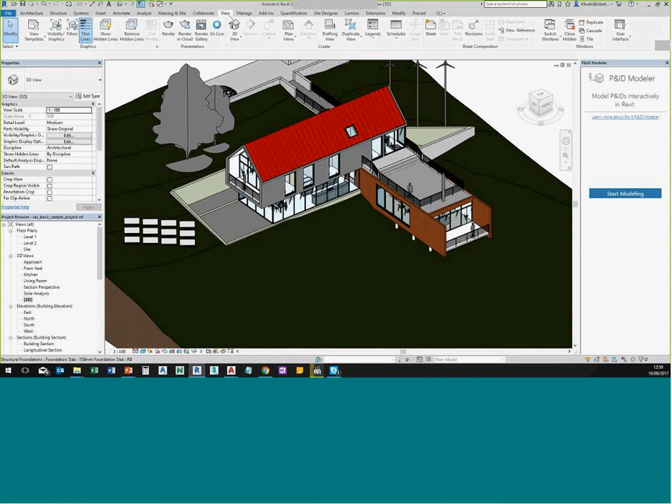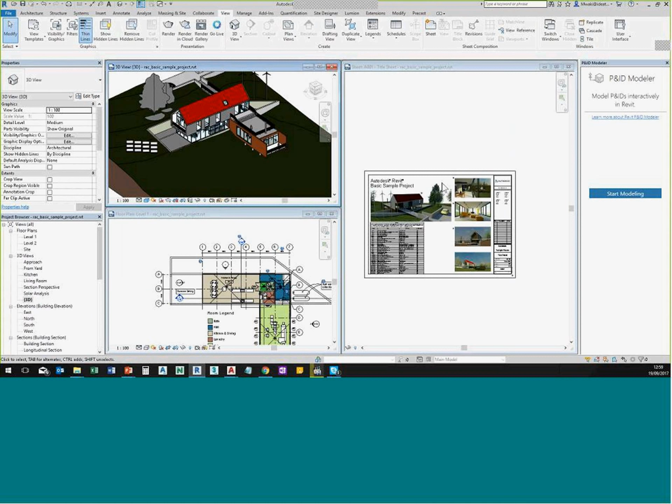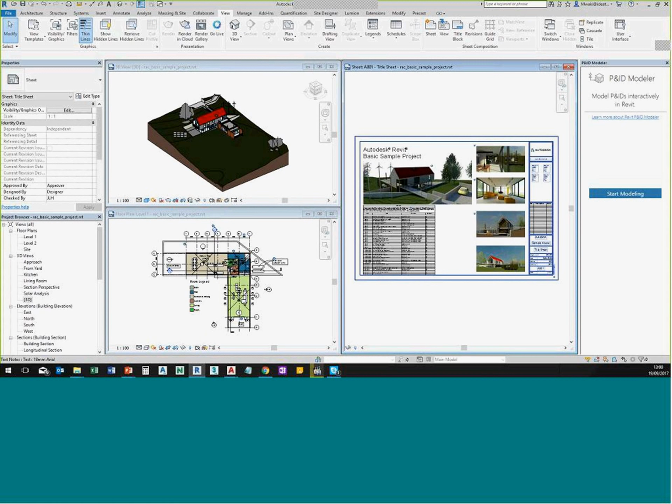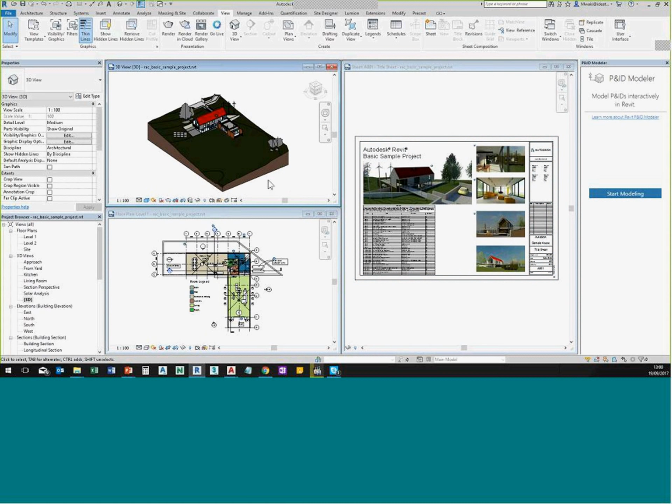So I'll go to my View tab and type Windows. You see, so I'll open this and say zoom all to fit so that all of those can zoom into place. Now, all these are model space except, of course, this, which is layout, but it would translate to your paper space in AutoCAD, and this as your model space.